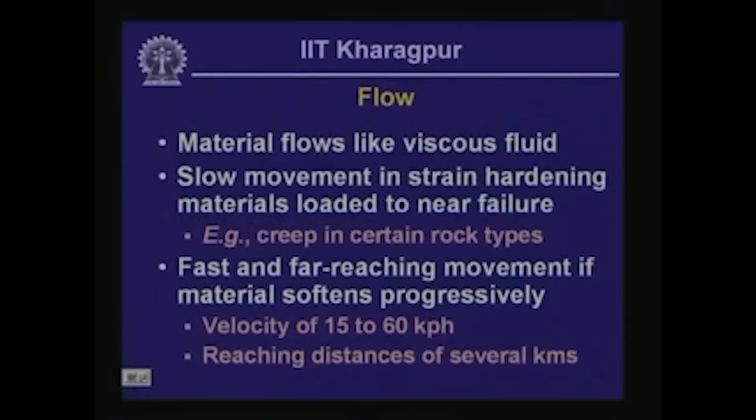There is another class of landslide which is called a flow slide. In this particular case, material flows like a viscous fluid, so-called, it moves just like a liquid, but one which has some viscosity. The movement could be slow in some types of flow slide, where the material has come to near failure and is strain hardening.